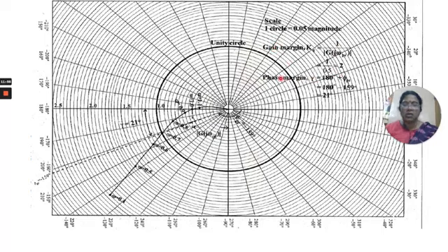Okay, so phase margin is nothing but 180 plus phi gc, where phi gc is minus 159, that is 21 degrees. So gain margin is 2 and phase margin is 21. And see, this is the critical point and your polar plot is inside the critical point. The system is a stable system. Okay.